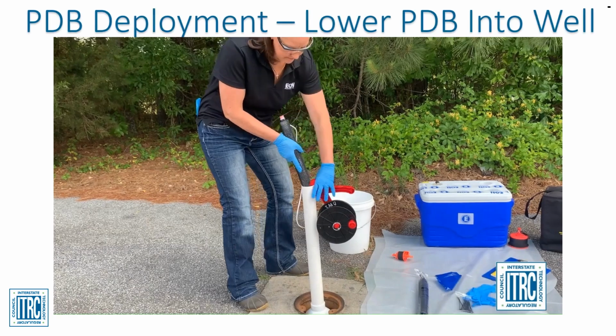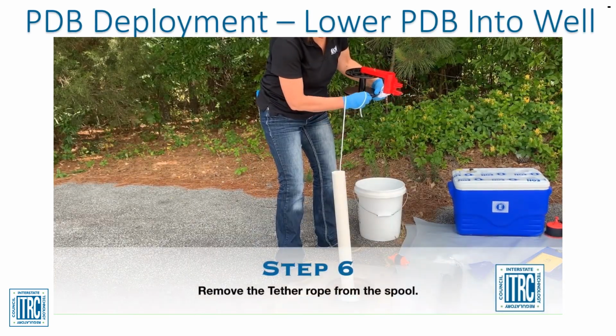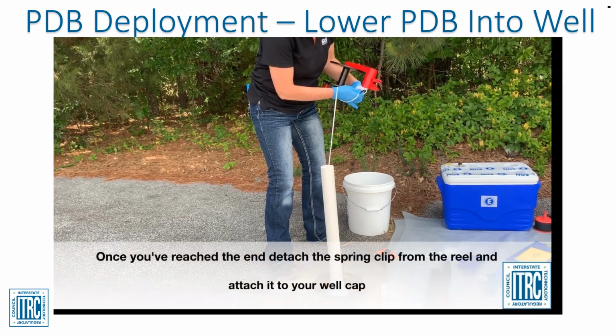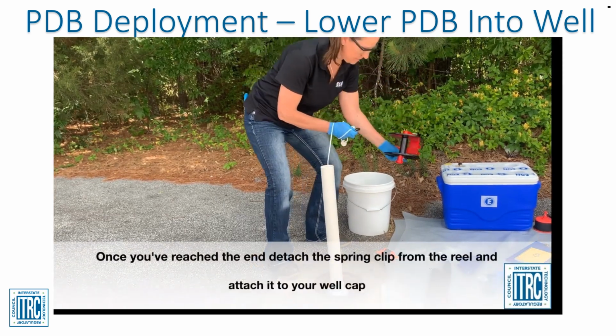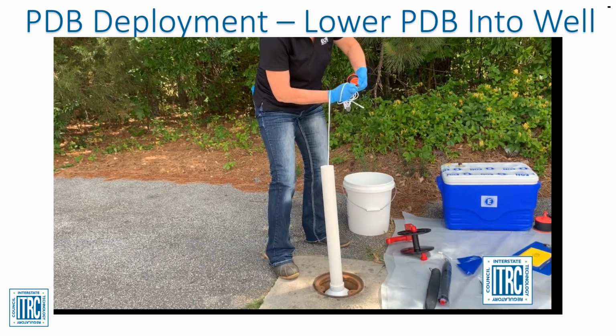Lower the tether and PDB until reaching the connection between the tether and the spool. Wrap the tether around one hand before detaching the tether from the spool to prevent accidental loss down the well. Unsnap the tether from the spool and snap it to the ring on the bottom of the well cap.